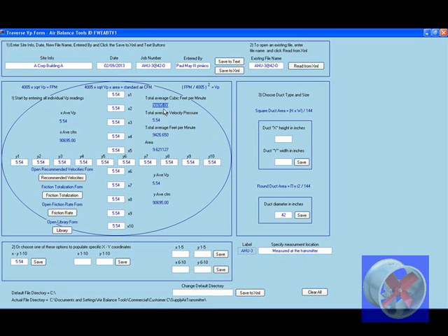So at 20 milliamps, a 5.54 transmitter means 5.54 inches of water, which is the same as this 9,426 feet per minute. This doesn't change. If our diameter changed, say we went to a 34, our CFM would change, but our feet per minute doesn't change, nor does our inches of water. So these are directly related.